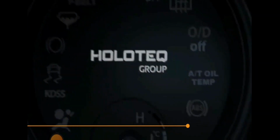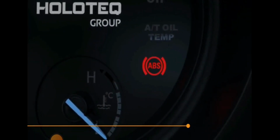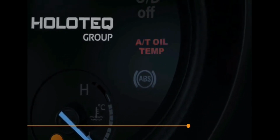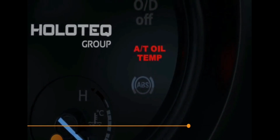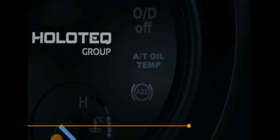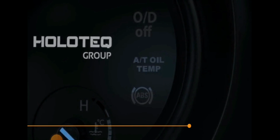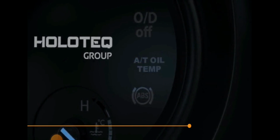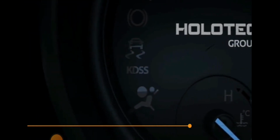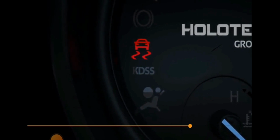Wheel ABS warning indicator. It indicates the existence of a fault in the ABS system. AT oil temperature rise indicator. Stop the vehicle in P position, and when the indicator is turned off, you can move. In case the indicator is flashing, go to the maintenance workshop because there is a technical fault. Sliding warning indicator. There is a fault in the system. Refer to the maintenance workshop.